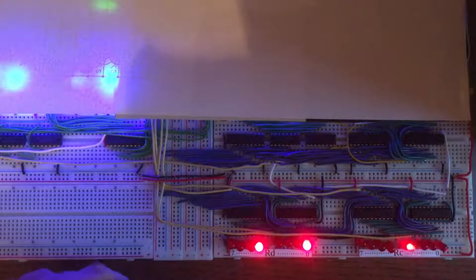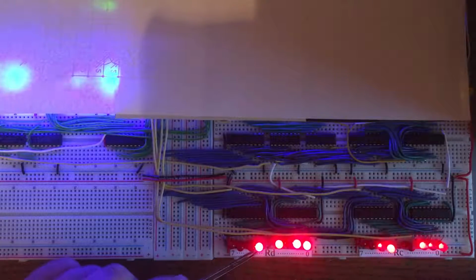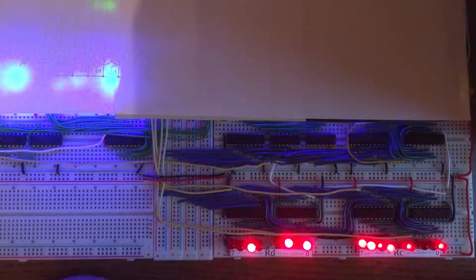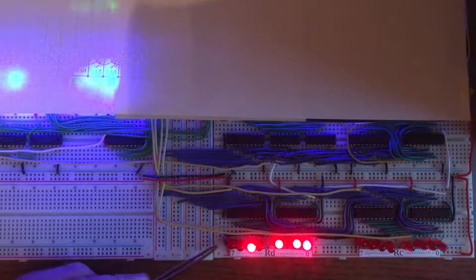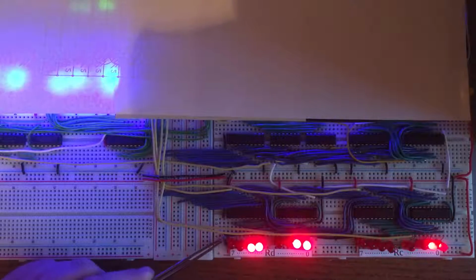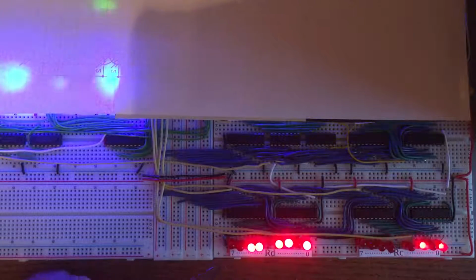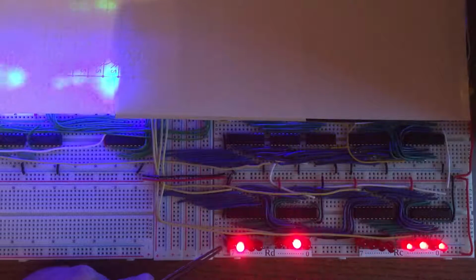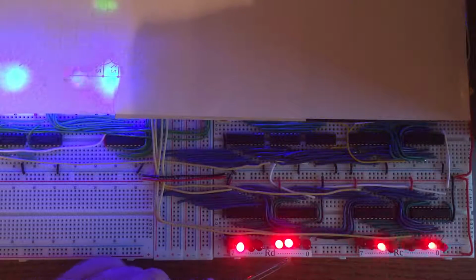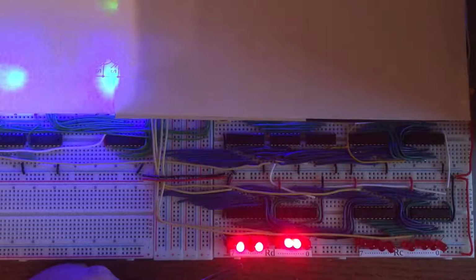And as I explained before, one of the side effects of organizing things that way is that these LEDs actually vary in brightness depending on how many of them are lit at the same time. But using that technique, we've certainly reduced the current from, let's say, 50 milliamps per LED down to, in this case, a maximum of 20 or 30 milliamps for 2 complete registers, for 16 LEDs. And that's certainly a big advantage. And as you can see, even if the brightness is varying, it's still perfectly possible to tell whether it's lit or not. And so for the operation of the computer, it really doesn't have any consequence.